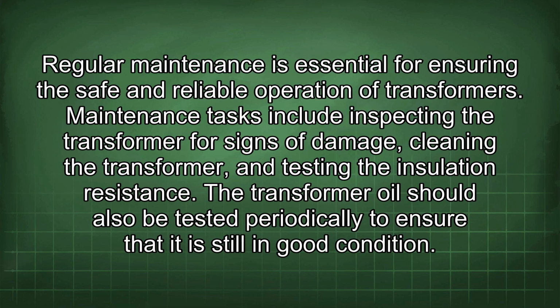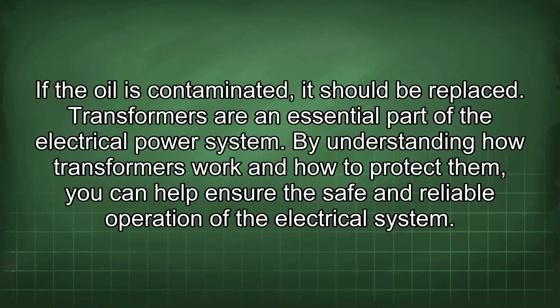Regular maintenance is essential for ensuring the safe and reliable operation of transformers. Maintenance tasks include inspecting the transformer for signs of damage, cleaning the transformer, and testing the insulation resistance. The transformer oil should also be tested periodically to ensure that it is still in good condition. If the oil is contaminated, it should be replaced.